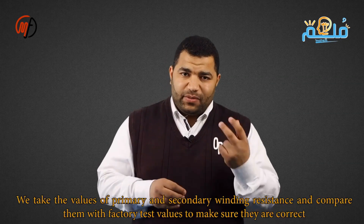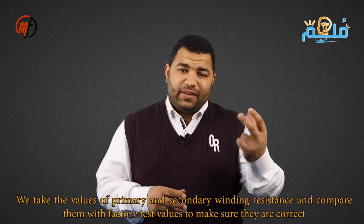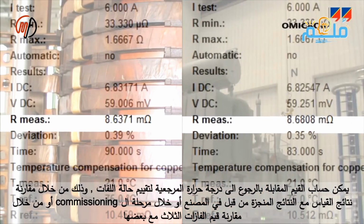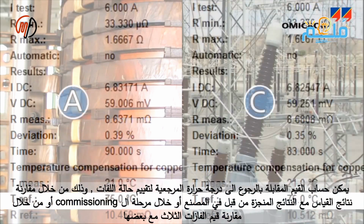We take the values of the primary and secondary winding resistance and compare them with the factory test values to ensure their accuracy. This can be done by comparing the measurement results with results from measurements performed in the factory or during commissioning, or with results from measurements of other phases.